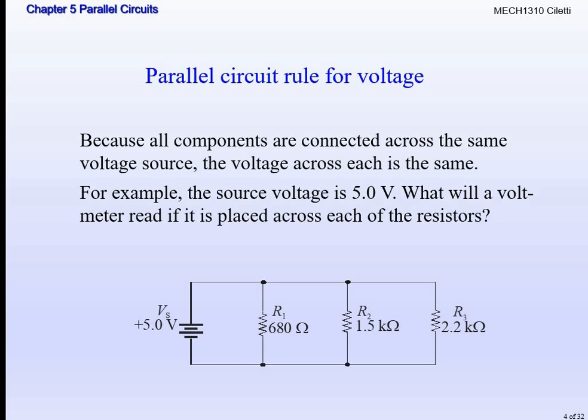All right, so very important for us. We're going to get to this. We're going to solve this entire circuit towards the end of the lecture here, so you'll be able to see that. But if we were to take a multimeter and turn it to voltage, obviously we're reading 5 volts DC here, so we have to be on DC voltage on our meter. And we put it across each terminal, okay? As the circuit is turned on, every single reading should say 5 volts.